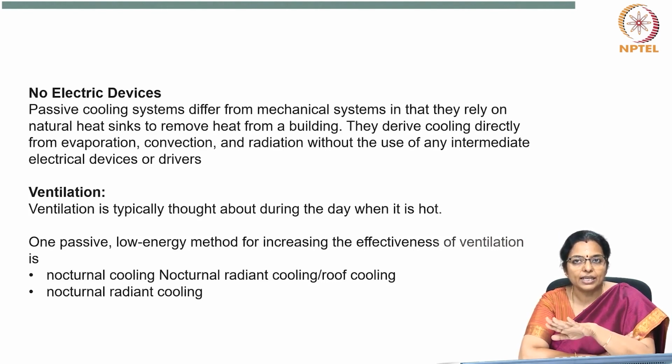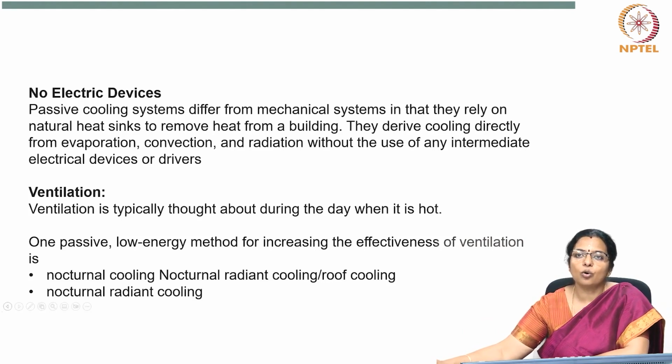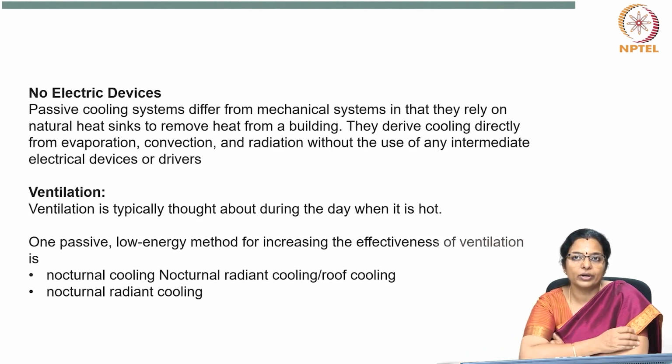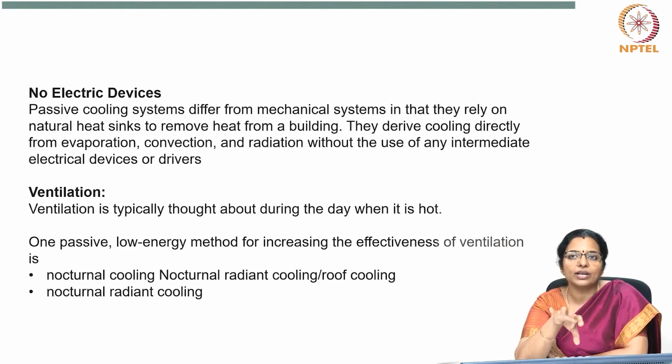When it comes to ventilation, ventilation is typically thought about during the day when it is hot. So, a passive low energy method for increasing the effectiveness of ventilation uses fans to flush heat from a building during the night. Such nocturnal cooling reduces indoor air and surface temperatures, essentially pre-cooling the building for the next day.